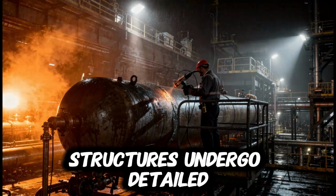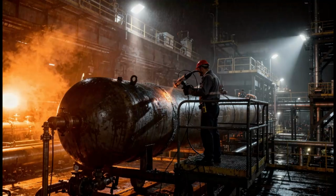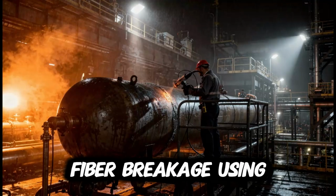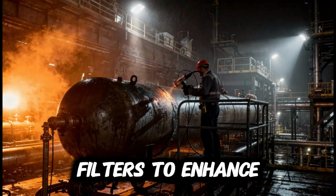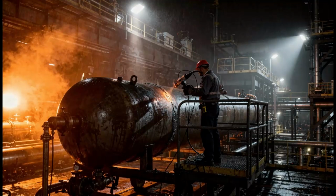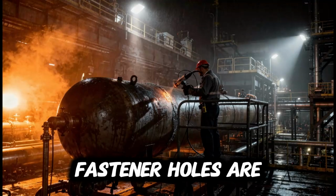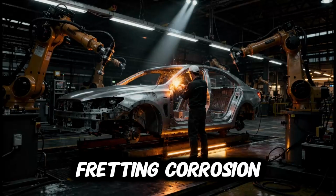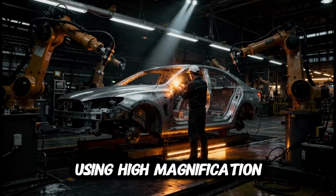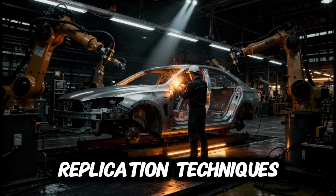Composite airframe structures undergo detailed visual examination for delamination, impact damage, and fiber breakage using controlled lighting angles and polarized filters to enhance contrast. Metallic components such as turbine blades, landing gear, and fastener holes are inspected for fatigue cracks, fretting corrosion, and foreign object damage using high magnification optics and surface replication techniques.